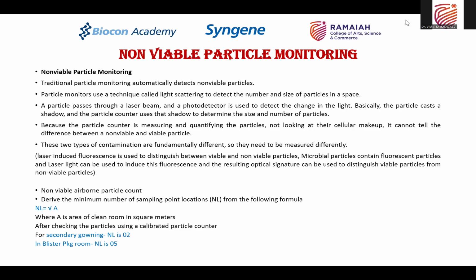So according to the standards, in a packaging room, at least from 5 places, 5 points from 5 different areas, this non-viable particle counting has to be done. While in the gowning area, the secondary gowning area, where the person changes gowns and enters the clean rooms, minimum 2 places, from 2 different locations, non-viable particle counting has to be done. All right. Now, this is about how many locations this counting has to be done.